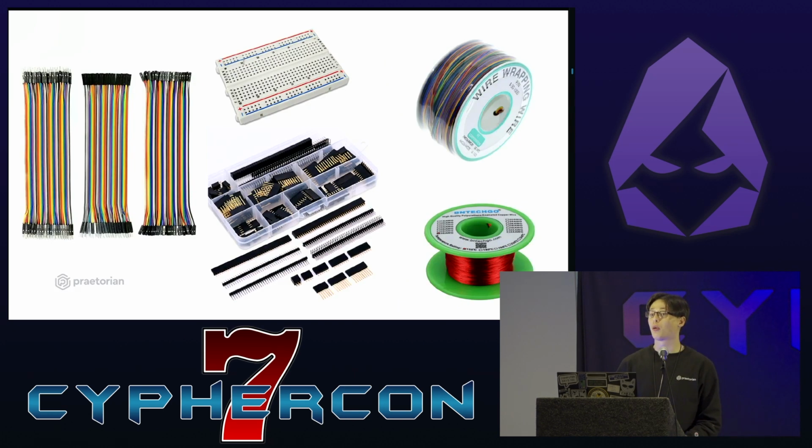Next, we've got to figure out how we're actually making some of these connections. Over on the left, there's some male-to-male, male-to-female, and female-to-female jumper wires. I like to treat these like they're disposable. I don't think any of them on the market are really great. You'll always have some where the electrical connectivity isn't perfect, and you'll spend a couple hours troubleshooting it, and you'll curse them and throw them in the trash. But at the end of the day, if there's no good option, just treat them like they're disposable.